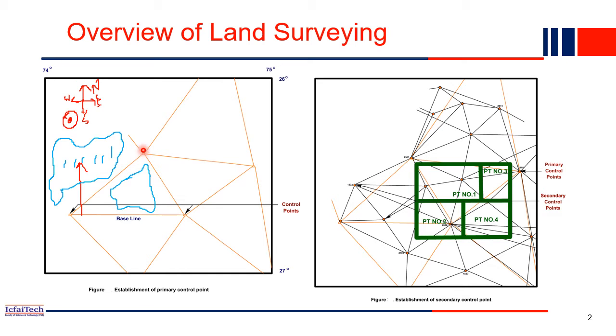Okay, so now we have to choose another point. Like that, in triangular fashion, we will cover the entire plot area. Whatever these triangles are, they are carried forward. The carried forward points have their graphical coordinates calculated from the measured horizontal distances and horizontal angles taken from the network of triangles. So with these points we establish this point.